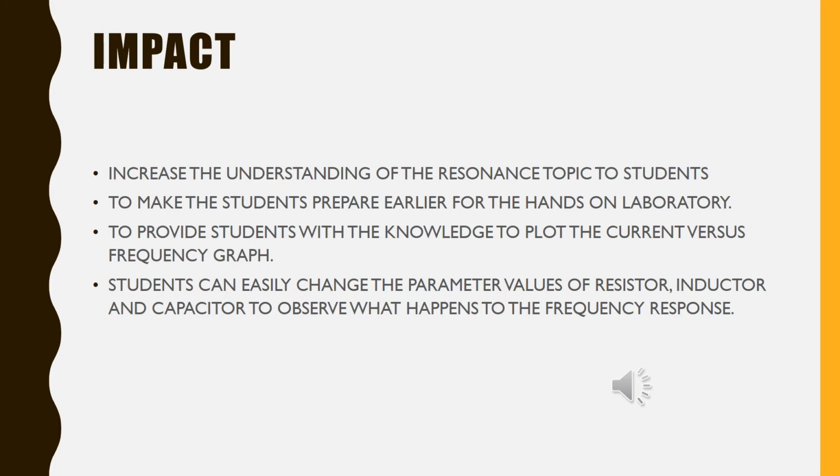Students are also able to easily change the parameter values of resistor, inductor, and capacitor to observe what happens to the frequency response. This is easily done because PSpice software can produce the value immediately from the software.